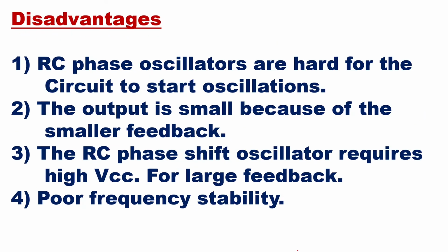Then if you see the disadvantages, here we have mentioned some disadvantages. RC phase shift oscillators are hard for the circuit to start oscillations. The output is small because of the smaller feedback. The RC phase shift oscillator requires high VCC for large feedback. There is poor frequency stability.